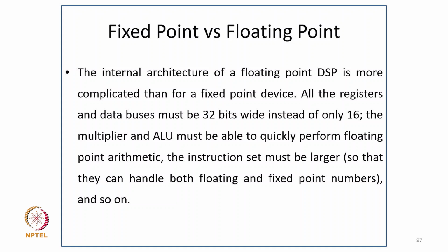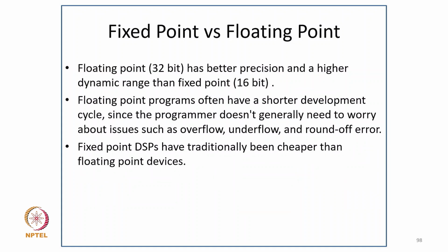All the registers and data buses must be 32 bits wide instead of only 16 bits. The multiplier and arithmetic logic unit must be able to quickly perform floating point arithmetic, and the instruction set must be larger so that they can handle both floating point and fixed point numbers, and so on.